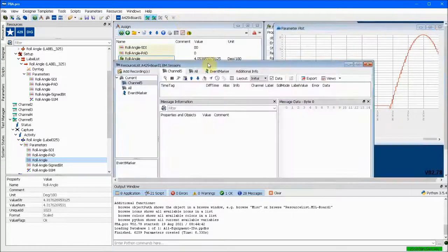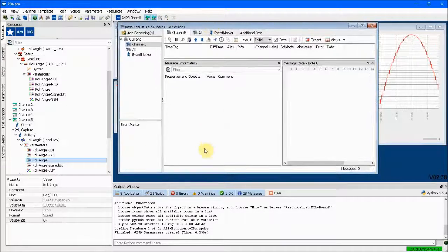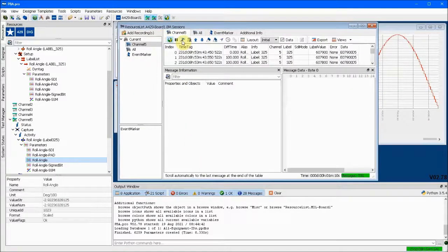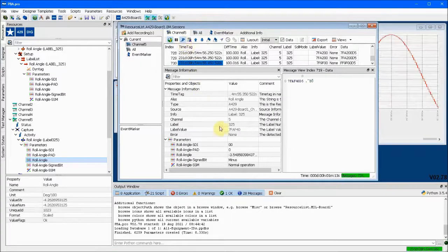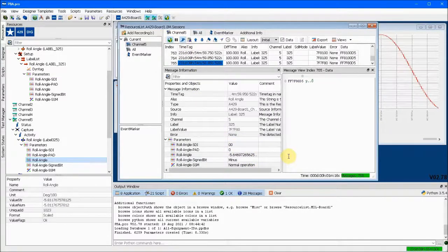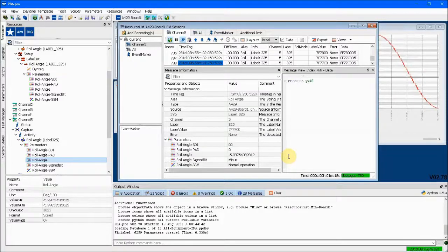As before, the recording display of the bus monitor function shows a summary of everything that is going on. These examples have included both transmit and receive, but just the transmit half of the example, or just the receive half, is useful for diagnostics, development, and debugging of actual ARINC429 equipment.